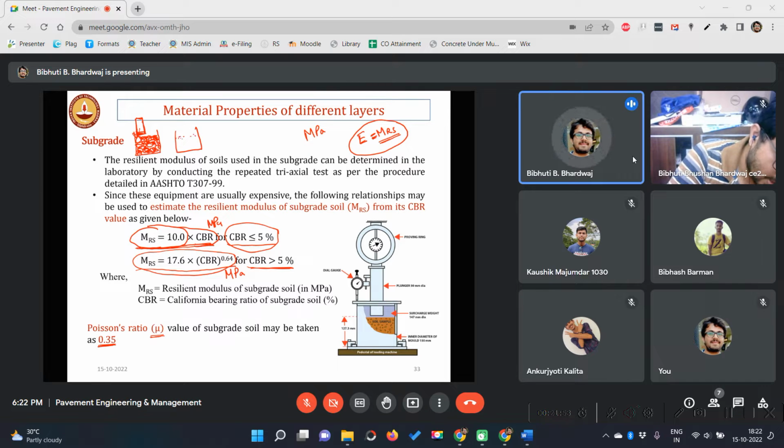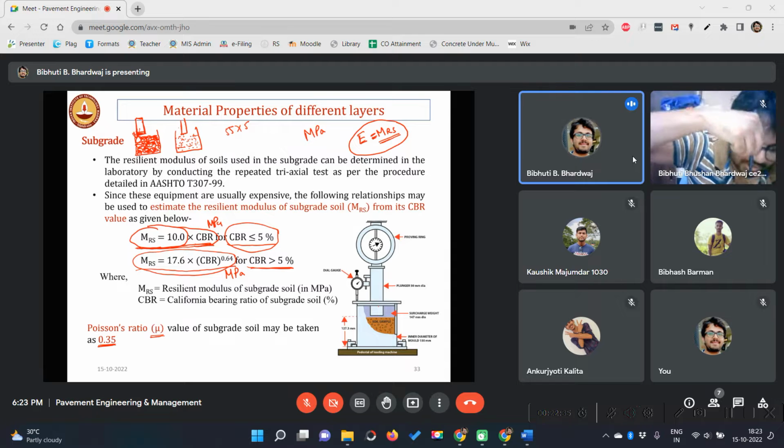And suppose here you have soil. You use the same compaction technique. Using a proctor, you compact it in 5 layers, like a modified proctor, with 55 blows in each layer, using the same hammer that you used in the modified proctor. Now when these two molds are there, one of aggregate and one of soil, if I use a plunger, it's like a big needle.